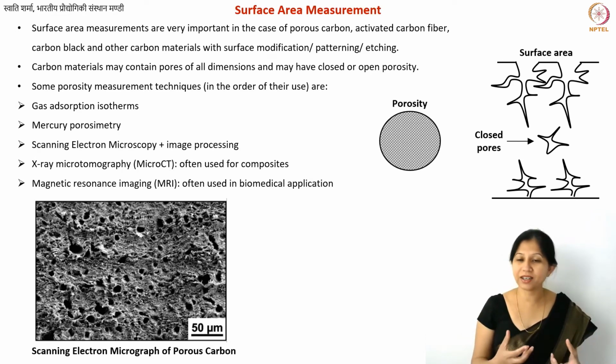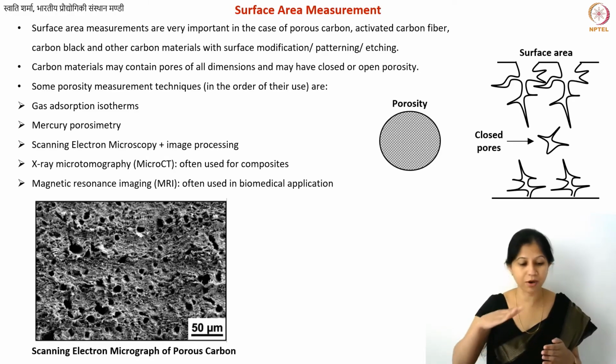The diamond saw will induce some defects, but it's not that bad, because anyway we are dealing with porosity and not microstructure right now. So if you want to get at least the information about how deep your pores are and whether or not they are cylindrical, that kind of information you can get by this kind of cross-sectional imaging.